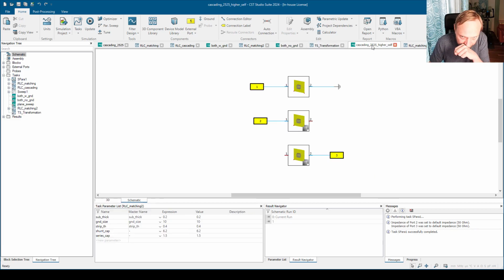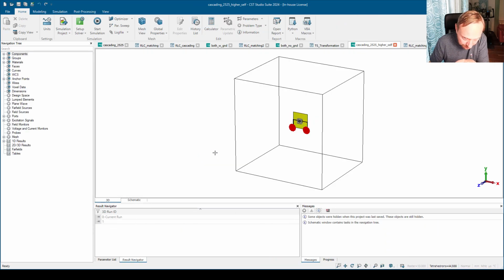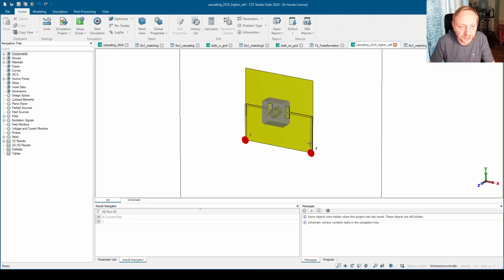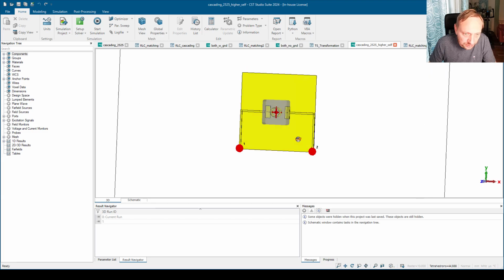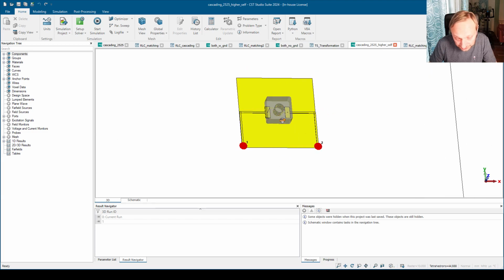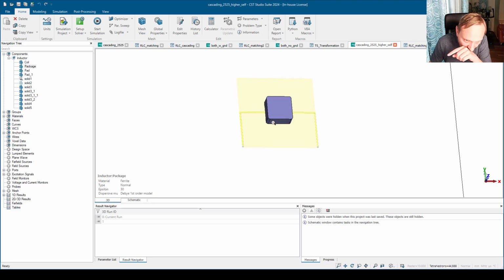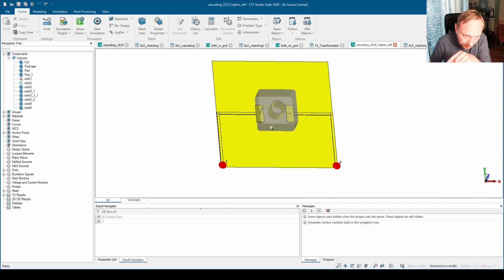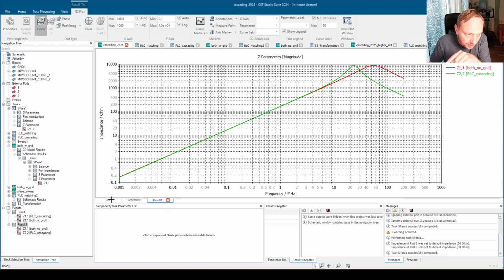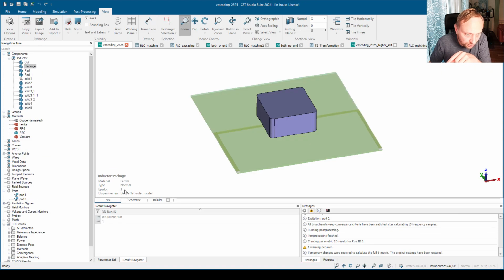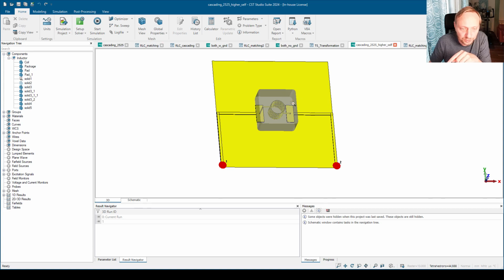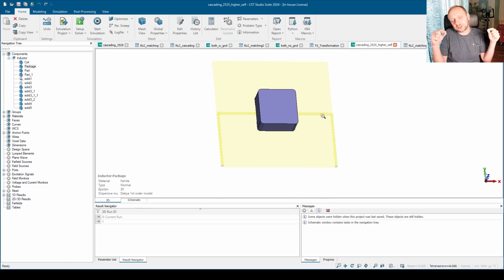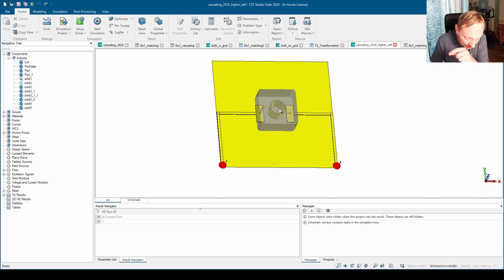Because if we make the following change, it's the same setup. I'm having the same inductor here. What I did is I increased the self-capacitance of the inductor. How do I do it? I take this model, which is a ferrite model, and I simply increase the value of the permittivity. In the original model, the permittivity has a value of 3. Now I increase it to 30, which means I am increasing the self-capacitance, but I keep the capacitance of the signal traces the same.